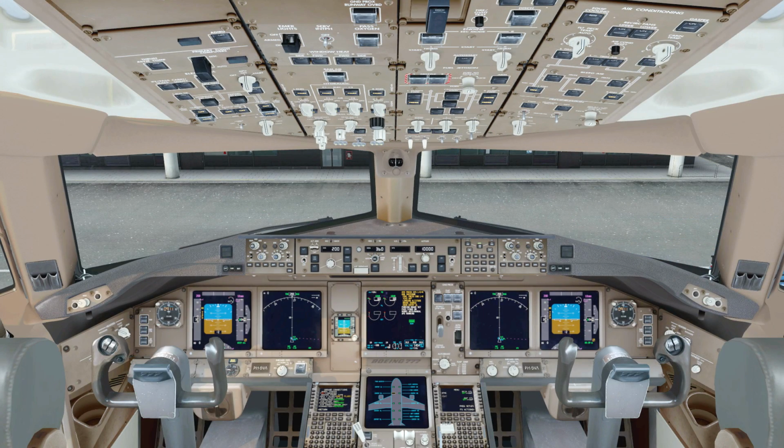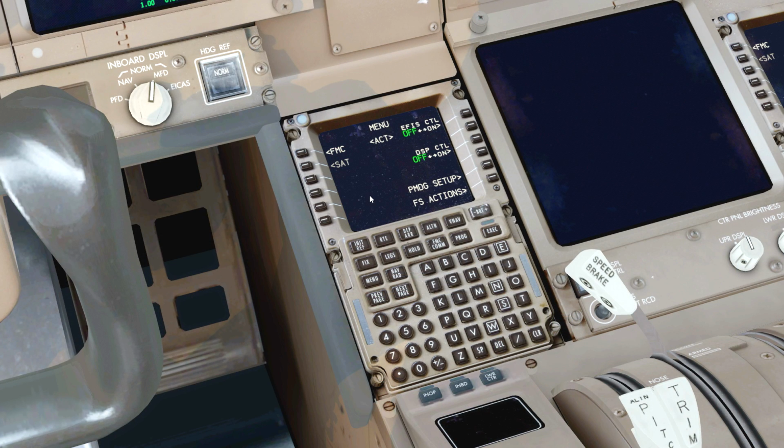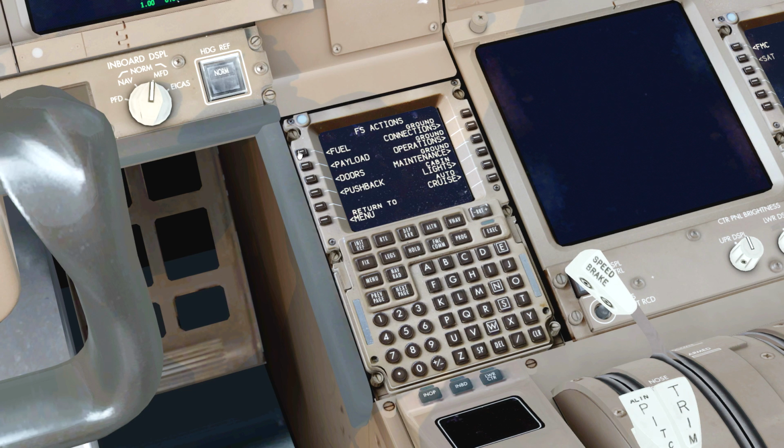So as you can see, we've now reached a state where the basics of the systems are started up. Basically what we can do now is program the flight management system and get our flight plan inserted. So this is how you will face the FMC once all the systems have started up. The first thing that you always want to do, before you go any further, is load the aircraft with the weight data that has been provided to you in your flight plan that you've created using PFPX or SimBrief or whatever flight planner you use.